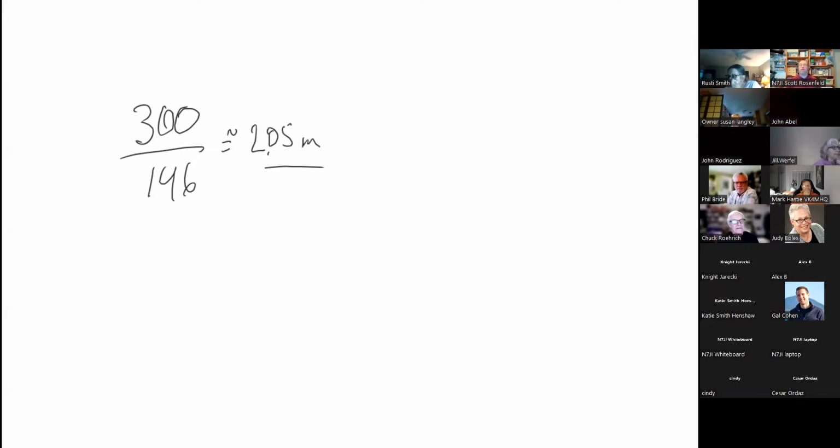That would be the 2 meter band. Remember we were calculating antenna lengths? That's your parity check to make sure that you're not losing your mind. If you know that the 2 meter band is 146 megahertz, you can make sure you're doing your math right.